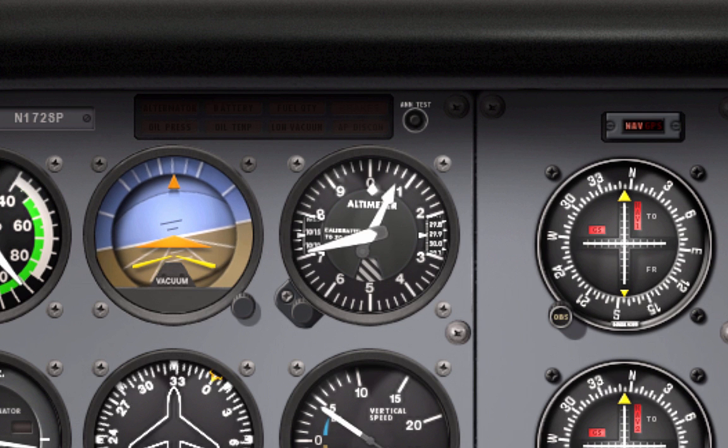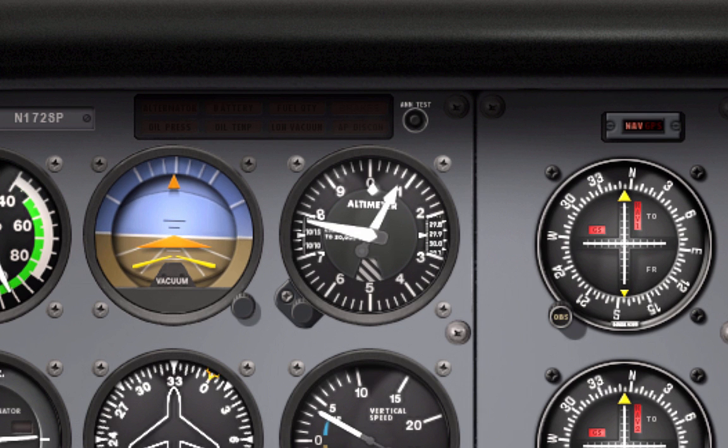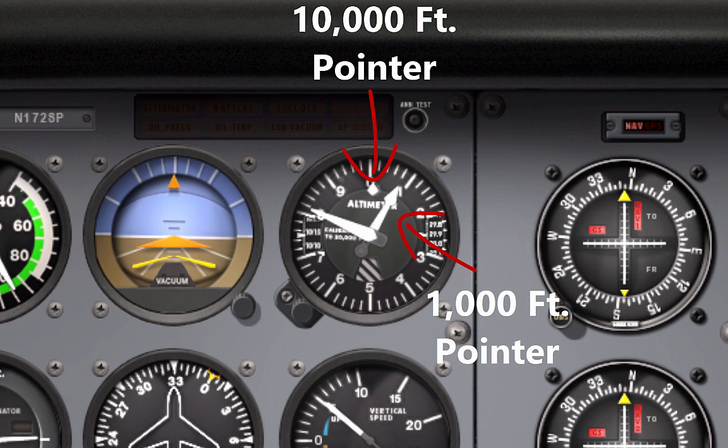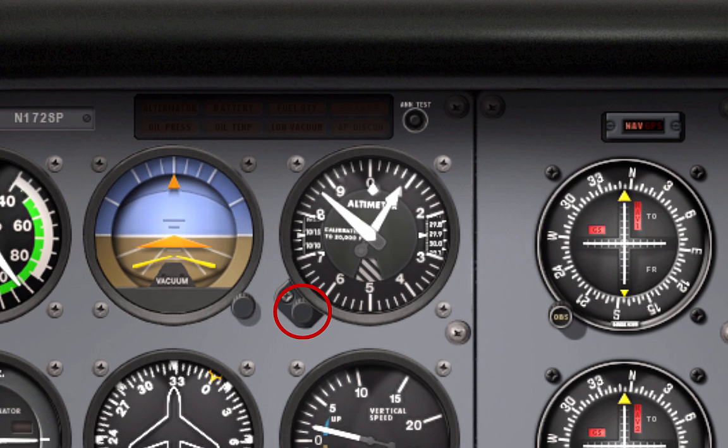The dial of a typical altimeter is graduated with numbers arranged clockwise from 0 to 9. Movement of the aneroid element is transmitted through gears to the three hands that indicate altitude. The shortest hand indicates altitude in tens of thousands of feet, the intermediate hand in thousands of feet, and the longest hand in hundreds of feet.